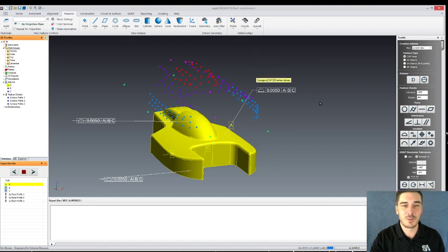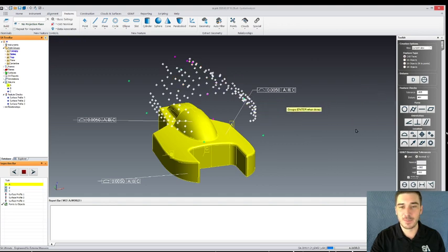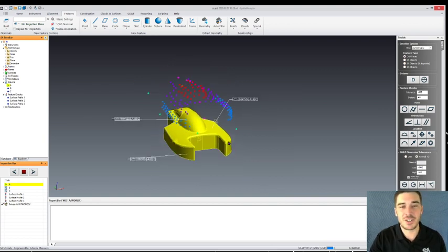And I'm going to select Groups to Object. I'm going to pick this group, this purple group, and the red group. And the object is, of course, our CAD model. And then all we need to do is just minimize these relationships. So I'm going to go to our instrument and go Locate, Minimize Relationships.